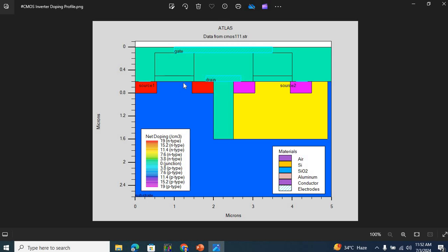We try to shrink the channel length by 0.7 times so that we can double the number of transistors, and we can double the functionality of smartphones, processors and memory chips at the same cost, because it's taking the same area. While there are other complicated features involved, like the cost of the mask increases if we keep reducing the dimensions, but anyhow, with almost the same price, we can double the functionality of our electronics. And that is what has been happening so far.